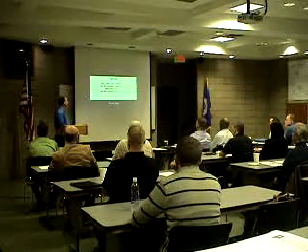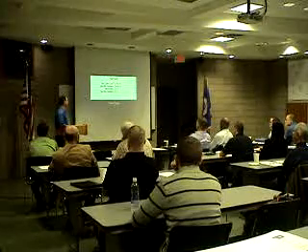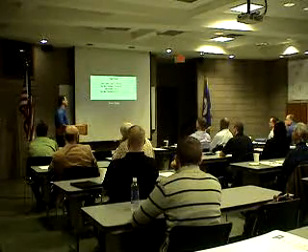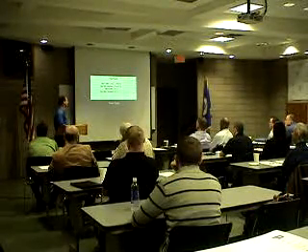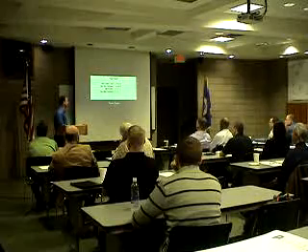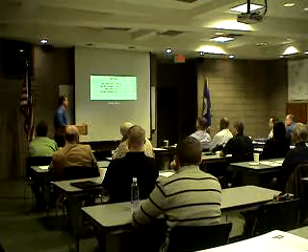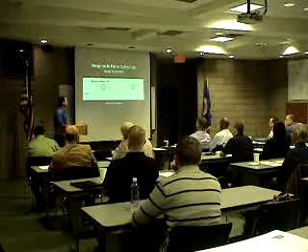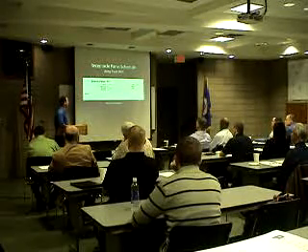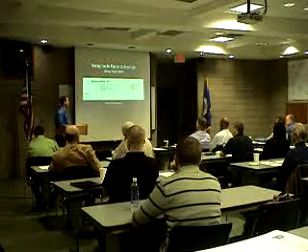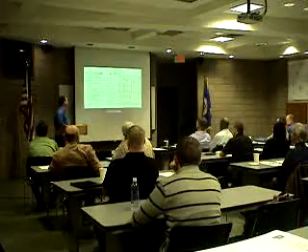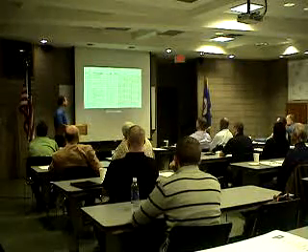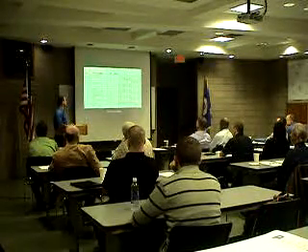For the panel totals, I ended up getting a total estimated demand of 282, total connected load of 313. And then when we planned for future sizing and future expansion of the building, we ended up getting a 500 amp panel. The receptacle panel, very similar. This one ended up being a 100 amp panel, 120/208. You can see how the circuit goes on here. Also 3-phase. Some things like the floor box is connected